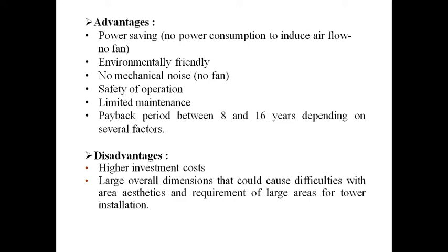Safety of operation, this is easier operation. Limited maintenance, as no mechanical devices are used here. Payback period between 8 and 16 years depending on several factors, like pressure, temperature, or airflow rate, etc. Limitations of the natural draft cooling tower: a higher investment cost, large overall dimensions that could cause difficulties with the area's aesthetics, that is beauty, and a requirement of a large area for tower installation.